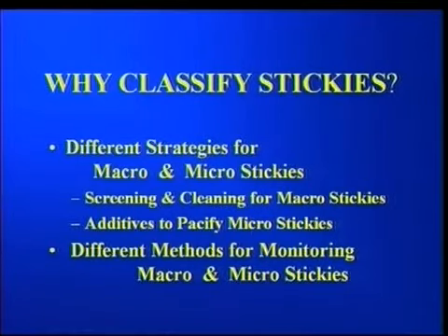For example, if you have too many macro stickies, that means the problem lies in the screening and cleaning system. As opposed to if you have too many micro stickies, the problem lies not with the screening and cleaning system, because most of these micro stickies will pass through the existing screens, cleaners, and other equipment.